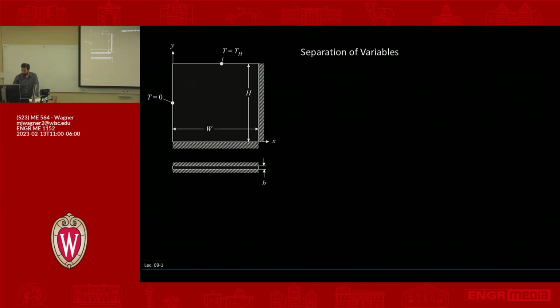OK, separation of variables. We start just like always with our control volume. So let's draw some differential control volume. We have to think about what this is going to look like. Before, we had a control volume, say top to bottom or left to right, all the way across the domain. But now we're modeling in two dimensions, so this differential control volume needs to be differential in both x and y. It's differentially small in both directions where we're modeling the temperature profile.